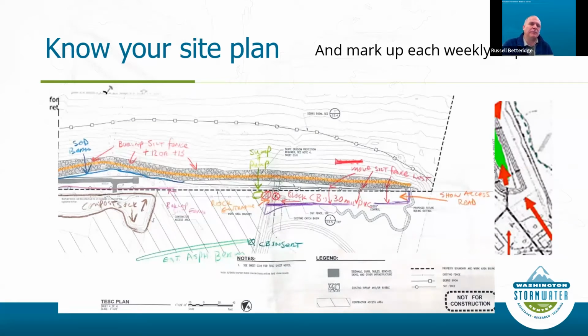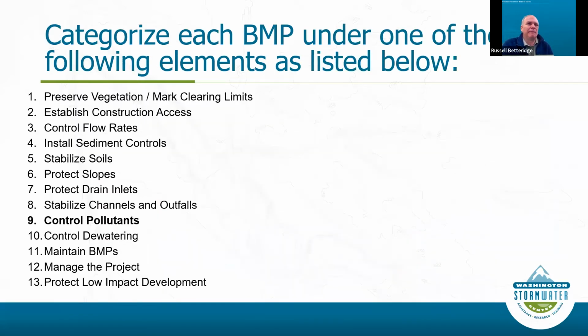This is our active plan. Put a date on it. Make sure people know that this is what we did during this time frame. You know, if there's a significant weather event, put that rainstorm down on there. How big was that rainstorm? What were your sample results? Have that all put together in that same binder.